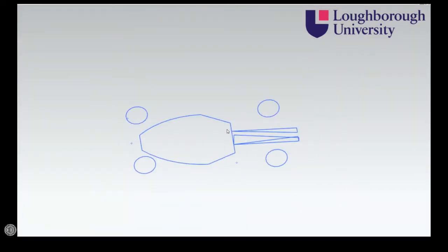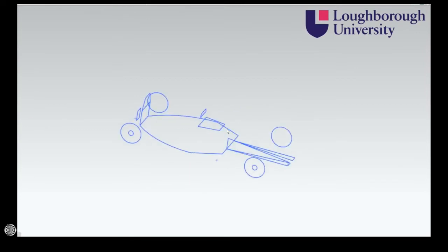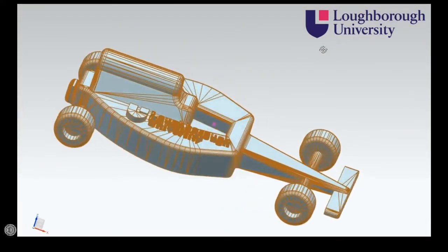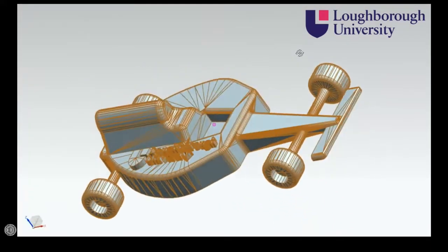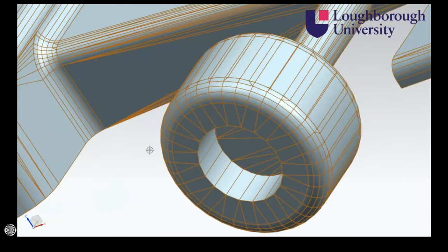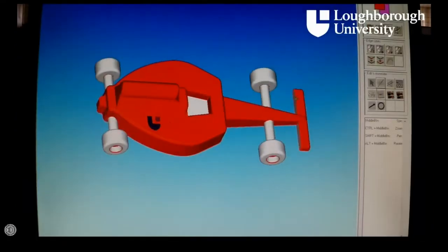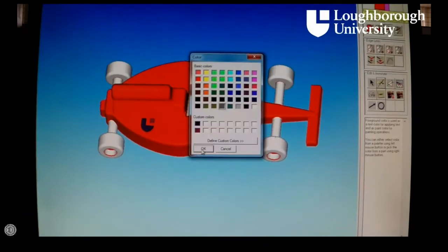The 3D process begins with the creation of a 3D CAD model. This can be done in numerous programs, including NX, SolidWorks, and many more. Upon completion, the model is converted to an STL file that is able to describe the surface geometry of the part by translating it into a number of small triangles. The STL file is then sent to the ZPrint software.